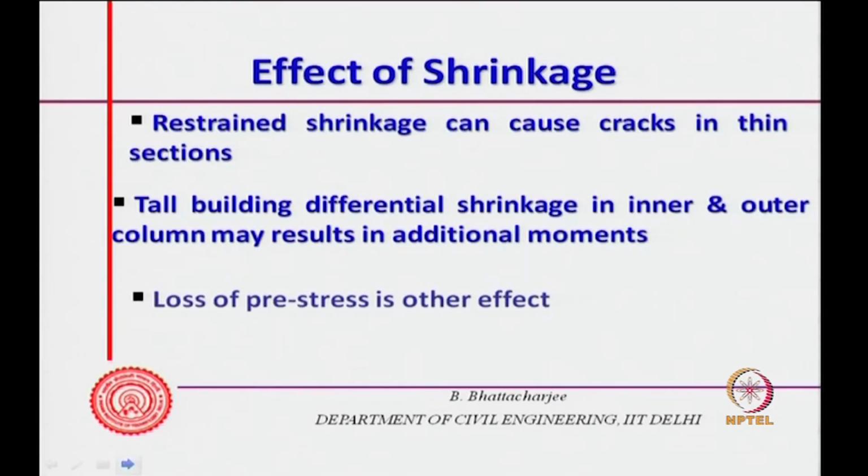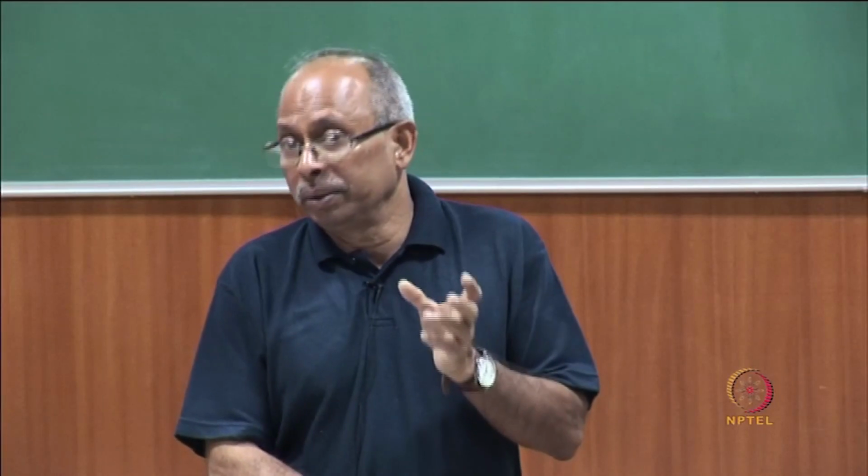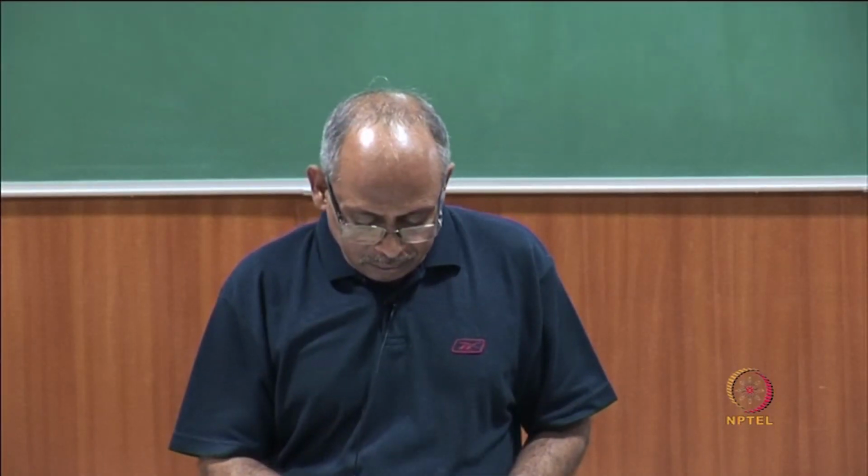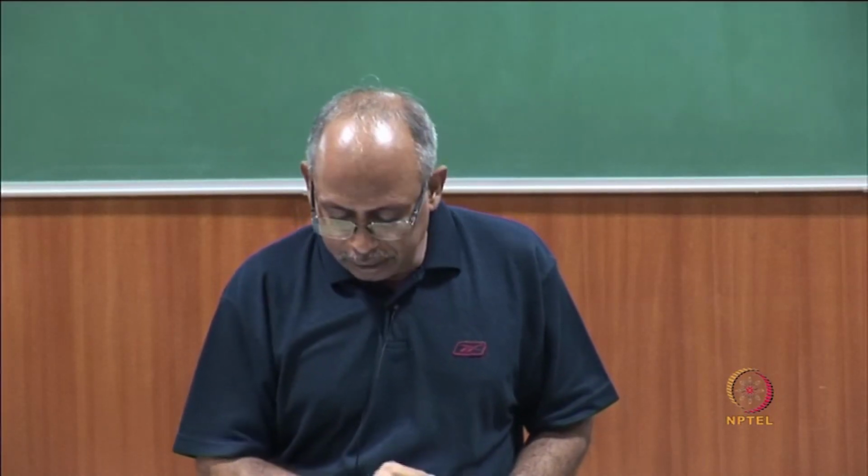Loss of pre-stress is, of course, the other effect, because shrinkage means the natural dimension of the concrete would become smaller. If it is restrained, this would cause loss of some pre-stress, because the concrete would have tried to come to this smaller dimension because of shrinkage, but you have restrained it. In other words, you are actually applying a kind of tension. So the pre-stress loss can be there because of the shrinkage of the concrete itself. This is another effect.